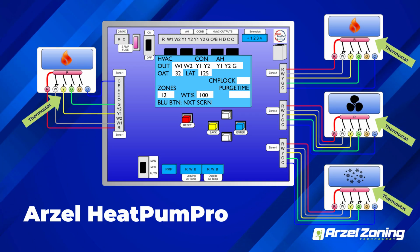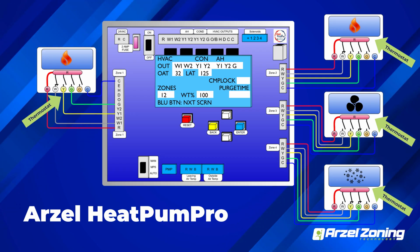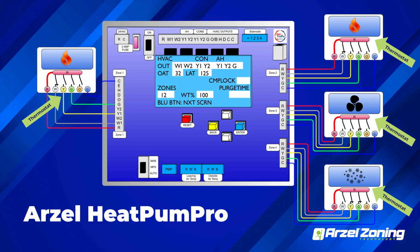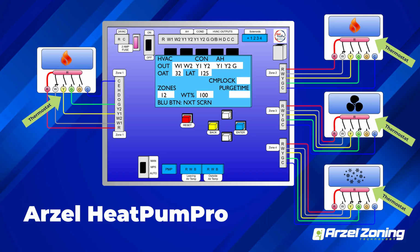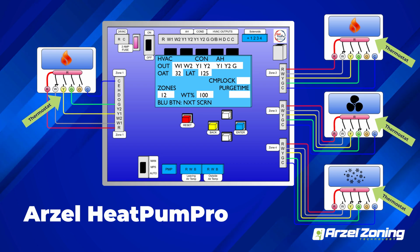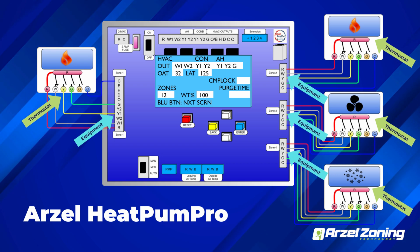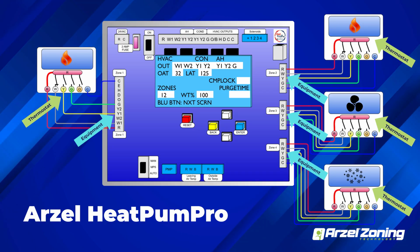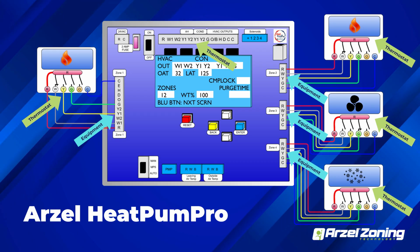Now, when we look at the zone panel, while we might not have all those same safety switches that you're going to have with your furnace, from like the draft proving switch and all that, those are all part of your furnace. But when we're diagnosing it, as far as the voltage is concerned, our thermostats are our thermostat, but our HVAC inputs, the zone terminal connections in the Arzel board, would be our equipment. In relationship to the thermostats, those zone connections would be our equipment. And then when we look at the furnace side of things, the HVAC outputs are a thermostat in relationship to the furnace.